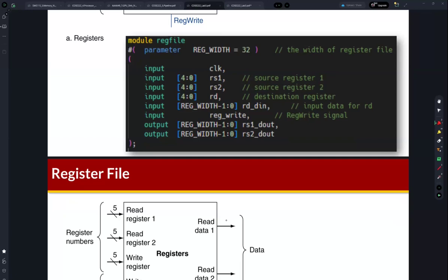So you can use Verilator, compile your SystemVerilog module and the test bench file, and then generate the compiled binary file. If you execute this compiled binary file, then you can get the waveform file. The output is the VCD file.